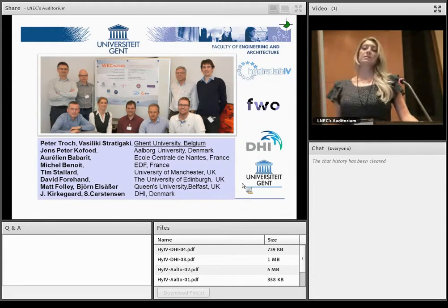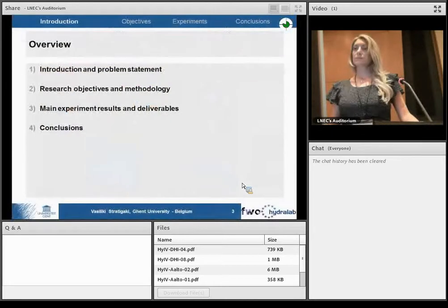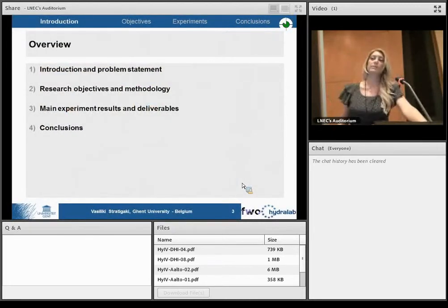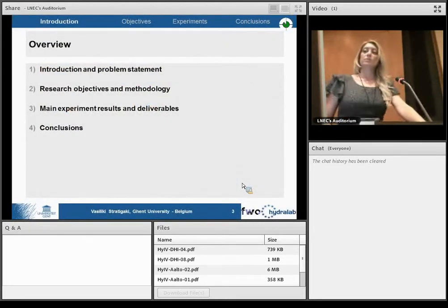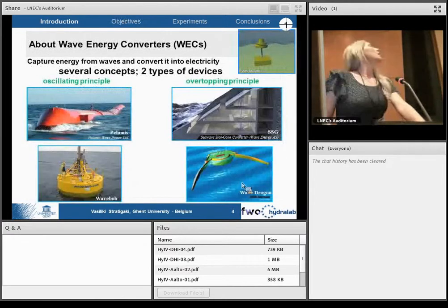But these large WEC arrays have problems with WEC array effects, which are distinguished in intra-array interactions and extra-array effects. Intra-array interactions occur between the devices within an array, which means that power production of the entire array may be smaller or larger than expected. In this panel, you can observe intra-array interactions. These green circles symbolize the plan view of 3 point absorber devices.